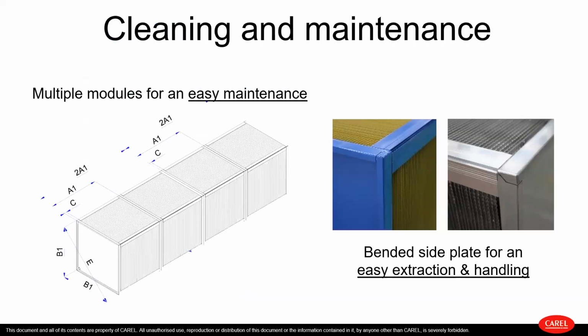Maintenance, we said before, it's really important. In such a system, you have dust in the air, so you have to clean the heat exchanger quite often. That's why you are not looking for really high efficiency, because otherwise these air gaps are really narrow. So you have wide fin spacing. Fin spacing, we can say more or less, could be 9 millimeters, 10, 11, 8, depending on the size of